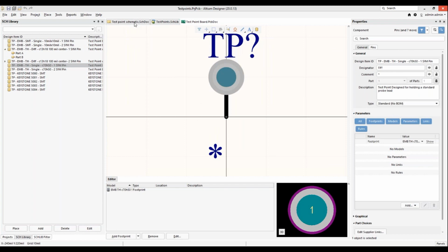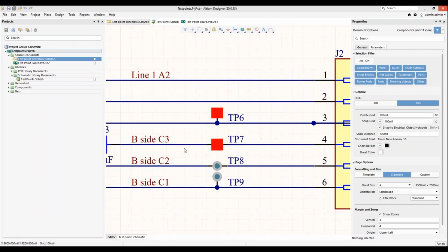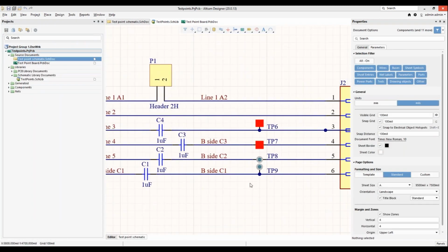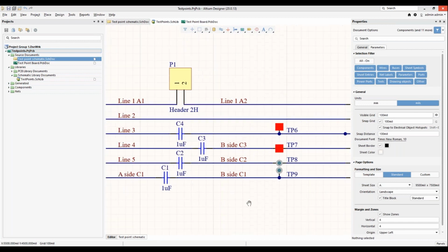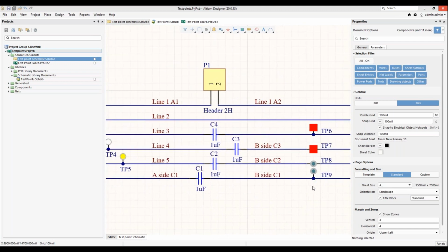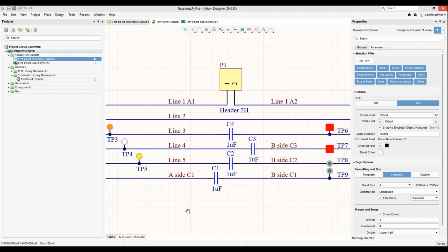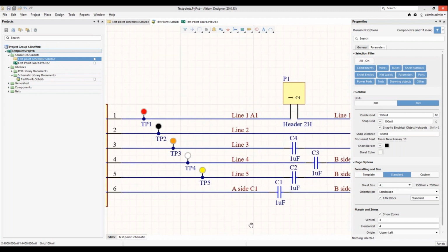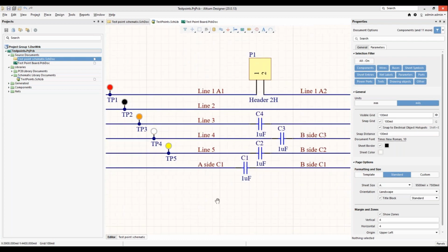What about on the schematic doc? Well, this just gives you an idea of what they are. When they are on the schematic doc, especially in Altium Designer, the netlist is going to push all this information through rather nicely. In theory, you could add these things in the PCB layout, but now you're putting the onus on the layout designer to do this. This really ought to be incorporated into the schematic design, and it keeps the netlist clean between the schematic and the PCB.